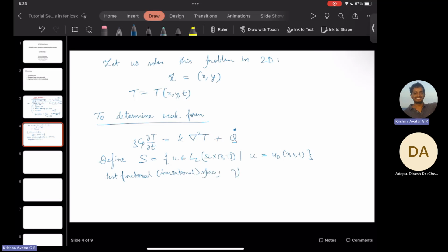In that we'll have v equal to all those functions v, and here we need not have them be a function of time. The thing is, in test functions we assume that the system is in one particular configuration, one particular instant in time, and then we are perturbing it. So it's as if we are taking minor variations about some time. As per classical mechanics, we don't consider the variations to be a function of time, because fundamentally they are virtual in nature, right?